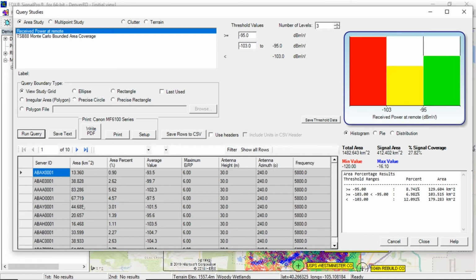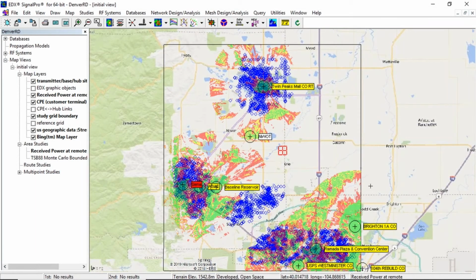Over on the left-hand side here for all of our transmitters, we can actually look at how much contribution each transmitter is making. So in that particular case, what we're looking at here for the entire area, we don't have very good coverage. This is the thing, however, since all I'm concerned about is covering my meters, my blue diamonds, I'm actually looking at a lot of area and reporting a lot of area that I'm not responsible for.